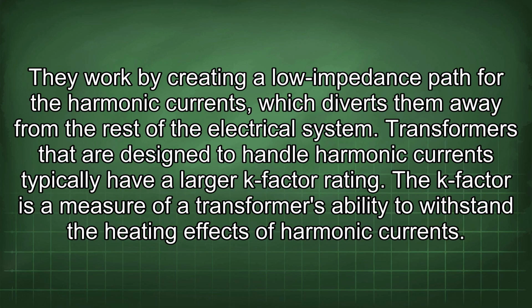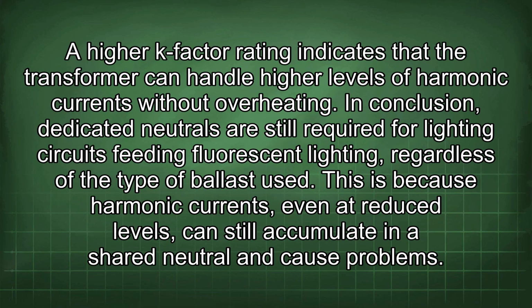They work by creating a low impedance path for the harmonic currents, which diverts them away from the rest of the electrical system. Transformers that are designed to handle harmonic currents typically have a larger K-factor rating. The K-factor is a measure of a transformer's ability to withstand the heating effects of harmonic currents. A higher K-factor rating indicates that the transformer can handle high levels of harmonic currents without overheating.